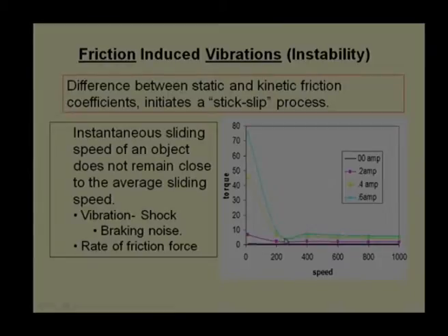And in this case particularly, if we are operating the brake at a speed lower than this, there is a very high coefficient of friction and quite possibly a jerky motion comes and stops the vehicle immediately, which should also be avoided. We should try to apply this kind of brake when the speed of operation is more than 400 rpm.